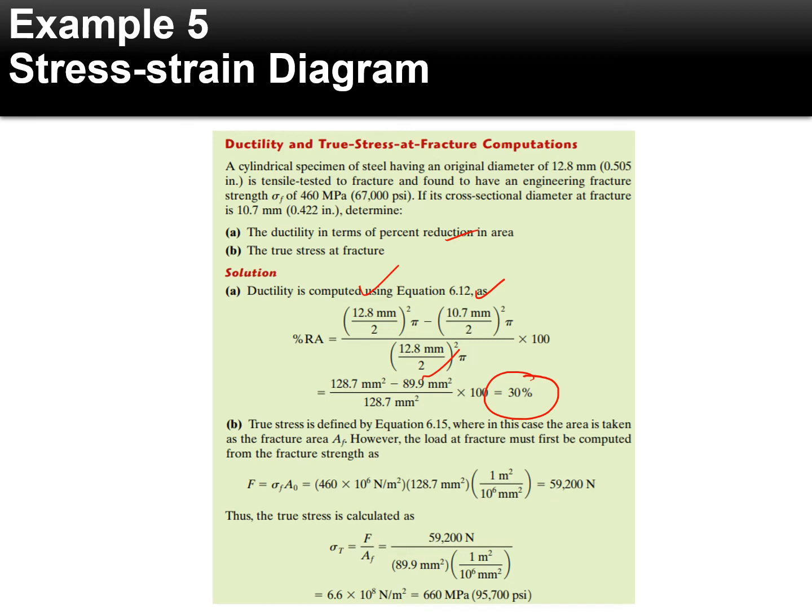From the Callister book, the fracture strain for brittle material is approximately not exceeding 5%. Then we call it brittle, which means that by the time it reaches fracture, the strain is less than 5%. So that way we can conclude it is brittle.